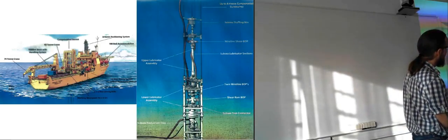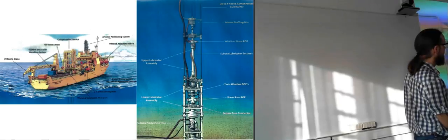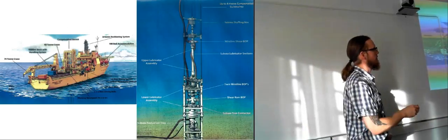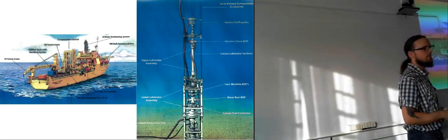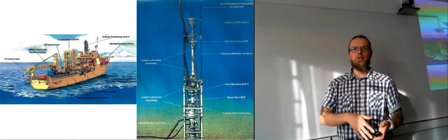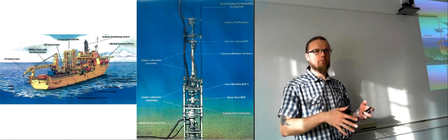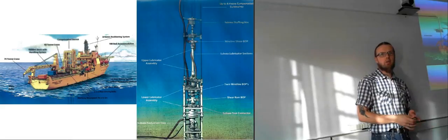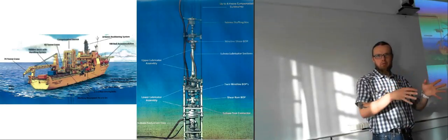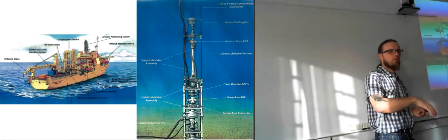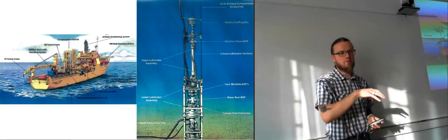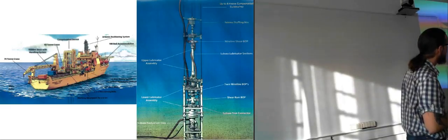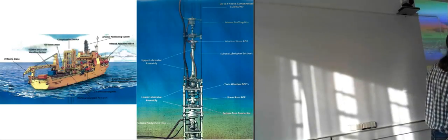So what they have is actually a lubricator assembly up here. I don't really know the details around this, but what I'm guessing is that the tool they're going to lower down needs some sort of lubrication on the sides in order for it not to snag completely. If it gets slightly narrower somewhere, it's supposed to just slide straight past instead of snagging on friction. So that's why it's being lubricated on the way down.